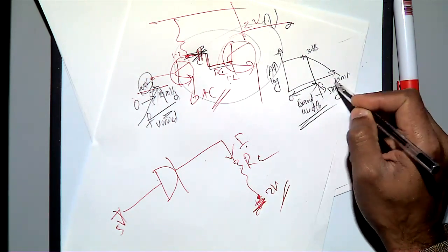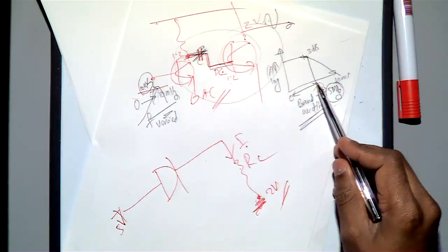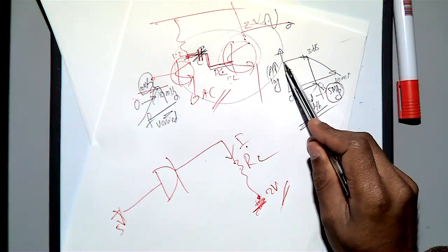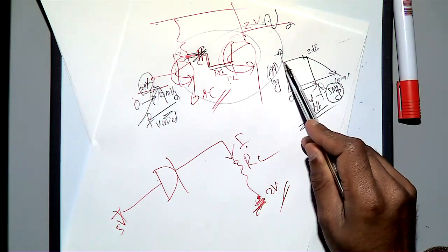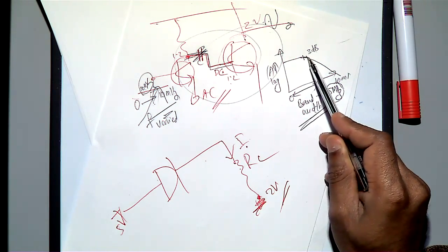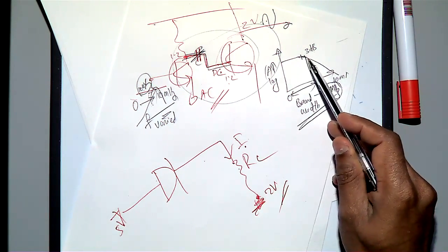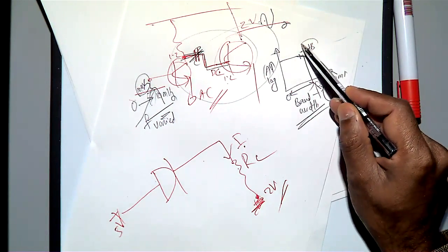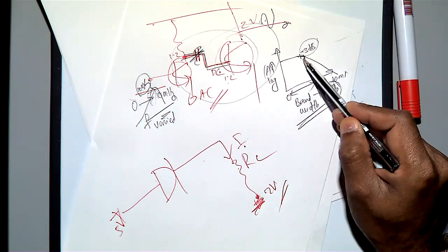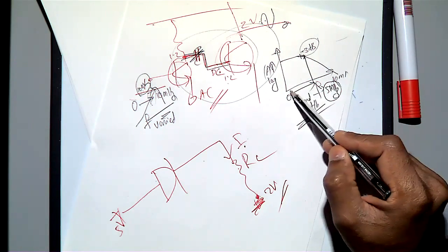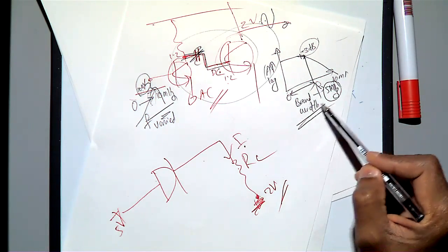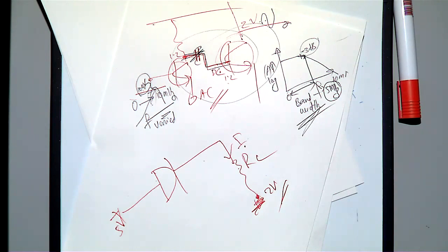So the bandwidth is 5 megahertz, meaning your gain is constant over that range of frequencies. After that, your gain is decreasing. The standard number is minus 3 dB. Here it is reduced to minus 3 dB, then we call this the bandwidth, the bandwidth of an amplifier. So your amplifier also has a bandwidth. Did you find out the bandwidth for your amplifier? How much was it?